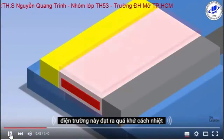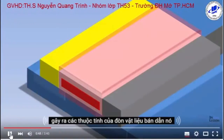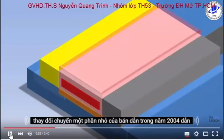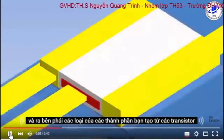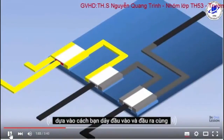This electric field reaches out past the insulation and causes the properties of the semiconductor material below it to change, turning a small part of that semiconductor into a full conductor, bridging the gap for any electricity flowing in from the left and out to the right. The types of components you create from transistors are based upon how you wire their inputs and outputs together.